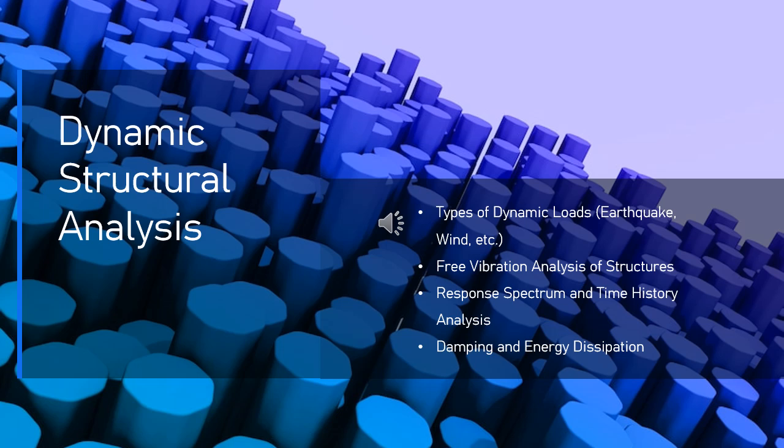Each mode shape represents a unique way in which the structure deforms during vibration. The first mode corresponds to the lowest natural frequency and typically involves the entire structure vibrating in a simple pattern, e.g., the entire building swaying. Higher modes correspond to higher frequencies and often involve more complex deformation patterns.